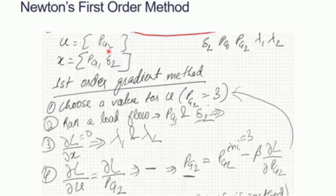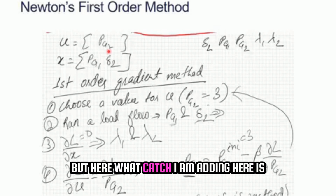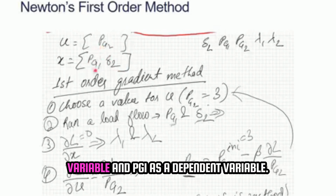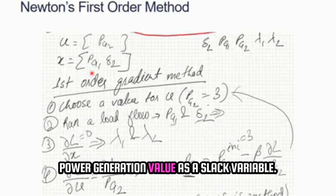There is a small catch here. You can keep both PG1 and PG2 as independent variables. But here, it is not necessary that you add both PG1 and PG2 as control variables. Here I'm adding PG2 as a control variable and PG1 as a dependent variable. The catch here is that generally in power flow, we have to keep one power generation value as the slack variable.